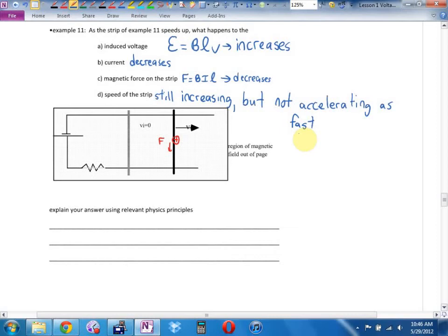Until there came a magic equilibrium point. You would maximize the velocity when the velocity was exactly inducing the same voltage as whatever your battery or power system was. So if you were hooking this up to a 1000 volt system, as soon as the induced voltage hit 1000 volts, it would now continue at a steady speed. You've maxed out your railgun. Does that make sense? And some nice review of right-hand rule stuff for your test next class.